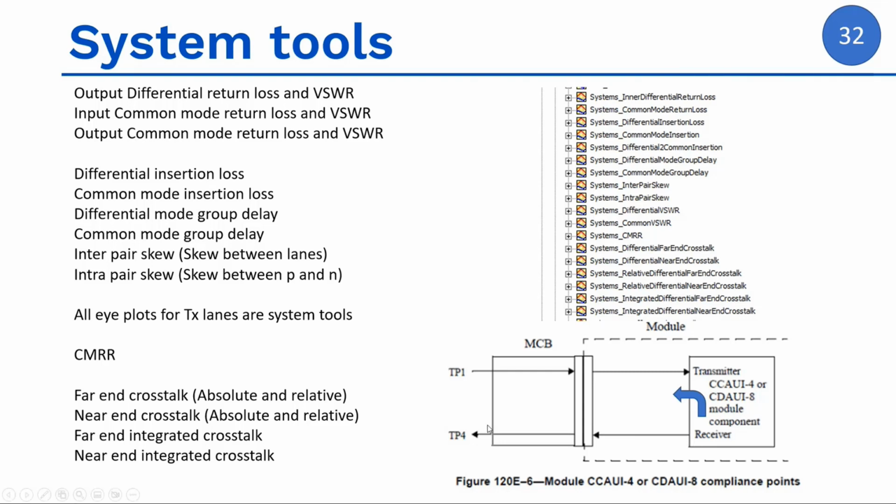By the way, I wanted to mention here, I left it as a note for myself. The eye plots, which we use to measure the RX side, you can use for the TX side too, but in this case it's going to be like a system tool. They also want to see, if we are receiving a clean eye, for example, from the host, by the time it reaches the chip inside the transceiver, what is it going to look like? What is the jitter? So you can also use the eye formulas graphs to do your investigations on the TX side, but looking from inside the transceiver.